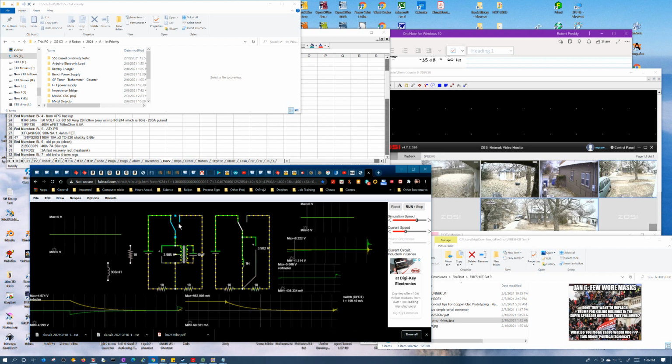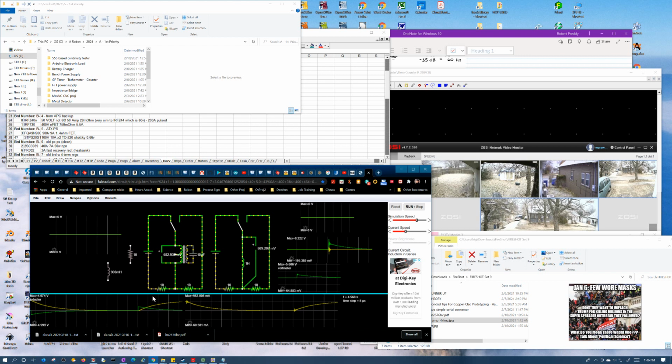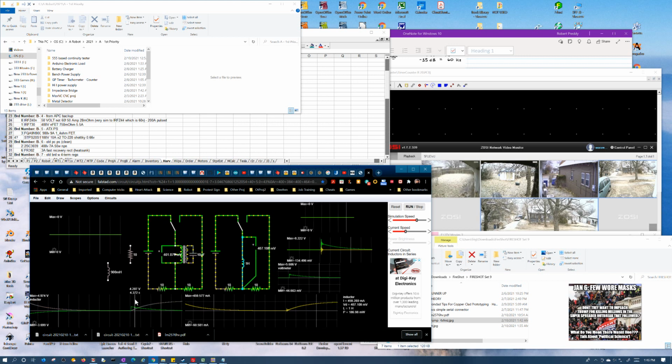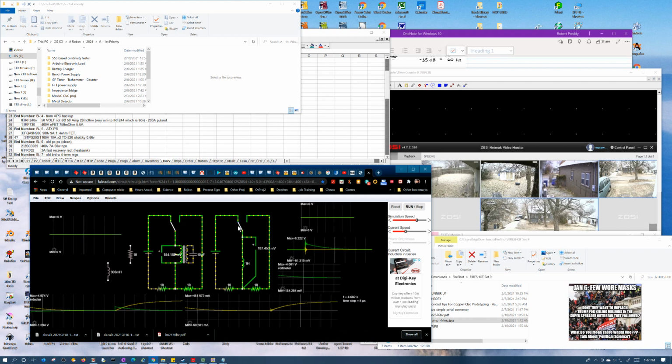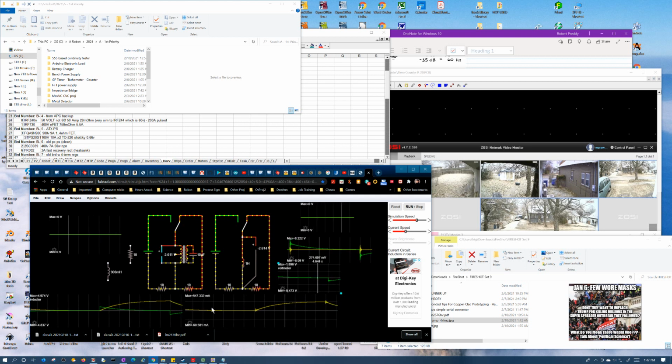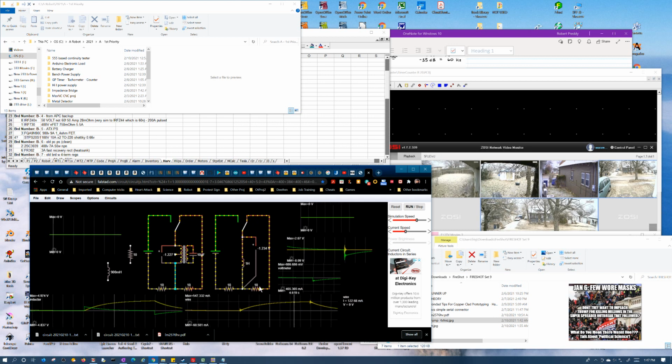So when we go charge it again, this is still acting exactly the same. Again, it's quickly damped because of the relative size of the capacitor versus our load. You're only seeing like 5 volts on this side, 5 volts on this side. Now let's give it a whack. Okay, now we're seeing -5 volts, and really -4.8 volts. Like I said, now that the impedances match, our charging voltage and discharge voltage happen to be equal.